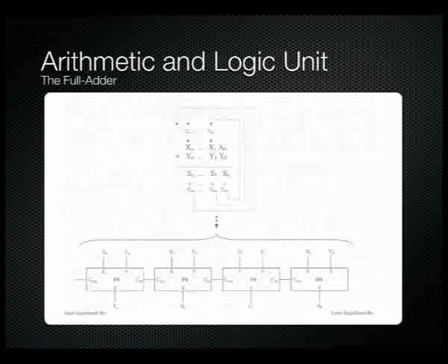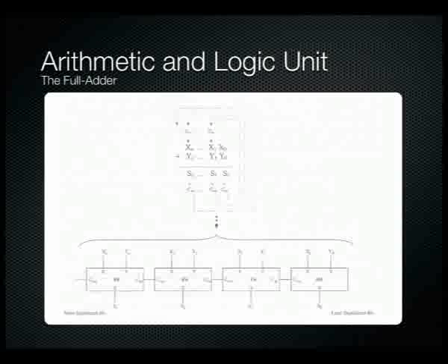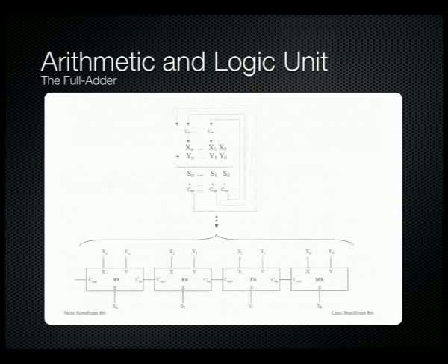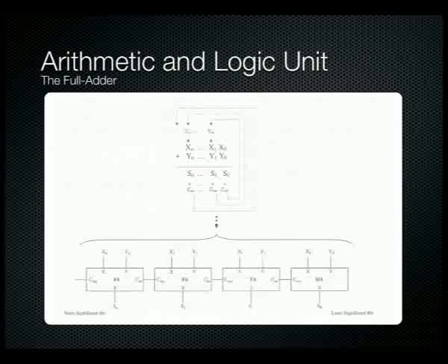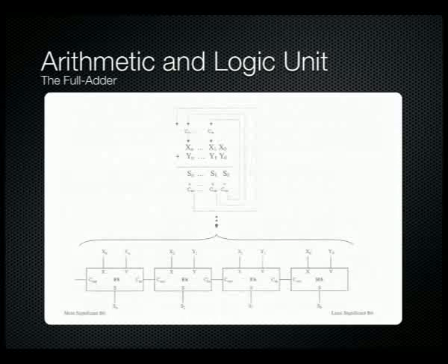So when it comes to using the full adder to do multi-bit addition, we simply use a cascaded approach where we add the least significant bits first. So we have a half adder on the least significant bit, we generate that full sum, and we pass the carry out bit into the carry in of the next stage next to it.